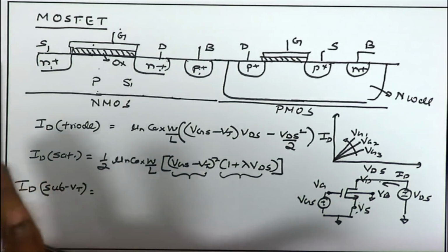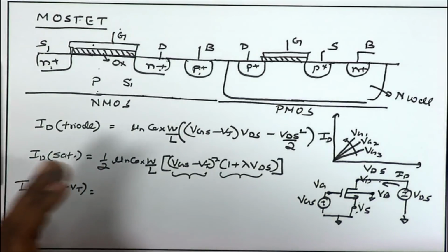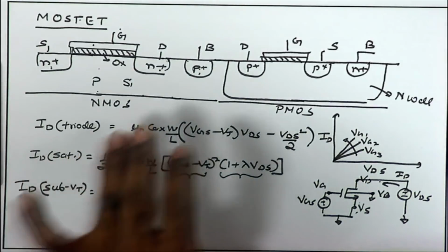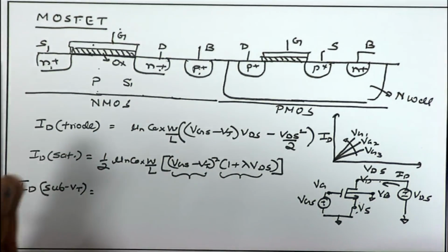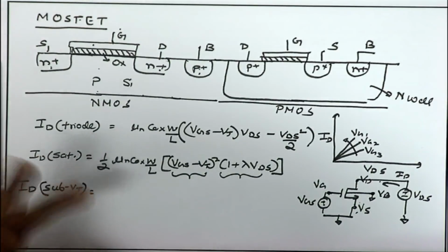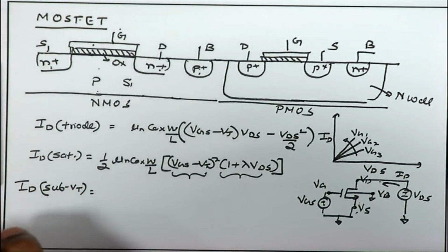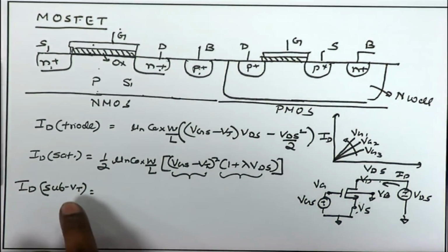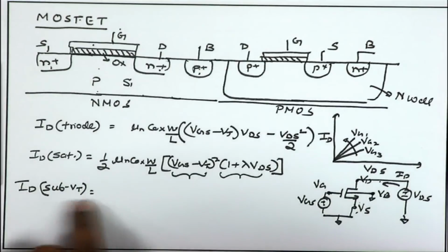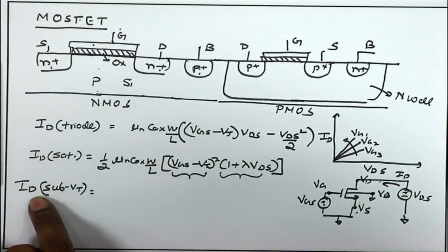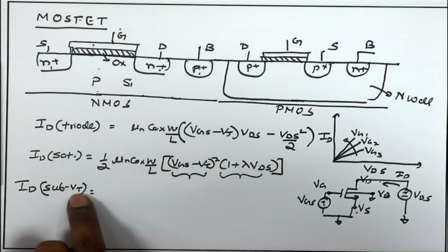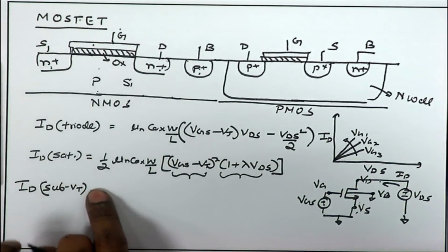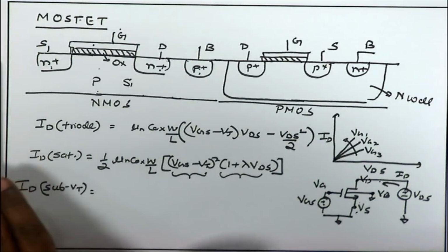So, the concept of power dissipation comes in a big way, whether we are talking about analog design, digital design, or mixed signal design for a power constrained environment, say a sensor node or a biomedical application, where the overall power budget may be very limited. In those conditions, we would like to aggressively scale down the supply voltages, and it can be even lower than or close to the threshold voltage of the device. And in that case, definitely the transistors are operating in the deep subthreshold regime.